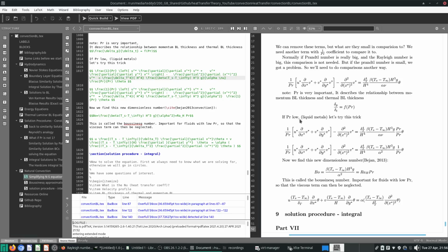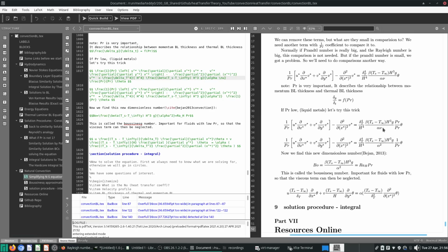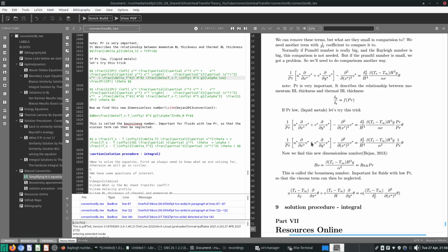Now within the thermal boundary layer for liquid metals is a different story. The main driving force will be the buoyancy forces. The main dispersion mechanism of momentum will then be the advection forces over here. Main driving force is this. Dispersion force will be this rather than viscosity. So this is the way momentum actually spreads throughout the fluid. It's with advection rather than viscosity. So that's what I was trying to say.